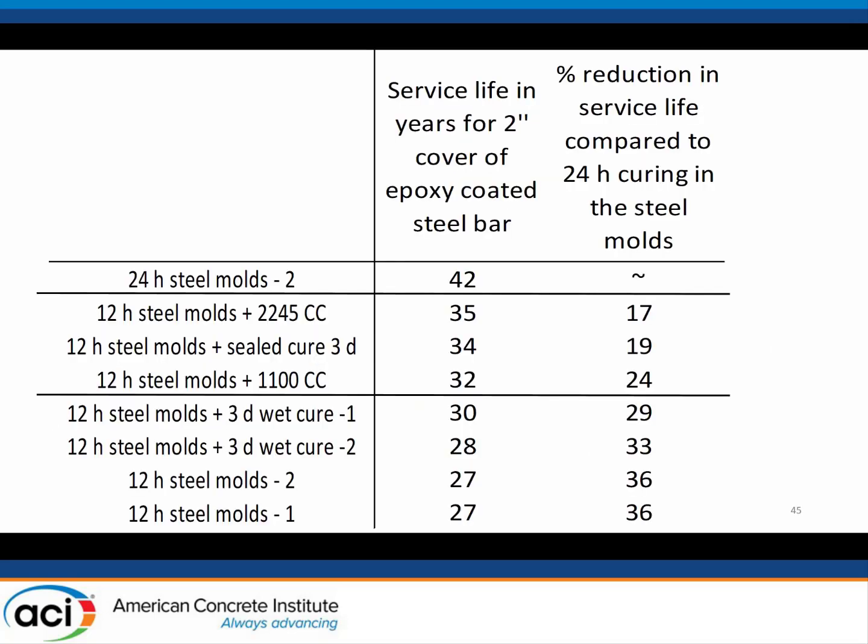And what this tells you is that, for example, if I left my molds in for 24 hours, right, I may have to just come down here and talk to you, take this to the audience so I can actually point to something. At 42 years is what the service life model says, 42 years. If I'm in Minnesota with 2 inches of cover with epoxy-coated rebar, that's what the model says, with chloride being the limiting thing that limits its life. What this says is these curing compounds, sealed curing, you get about 35 years. That's about 20% loss in life. That's what that says. You lose 20% of your life compared to leaving the forms on to use these other curing methods.